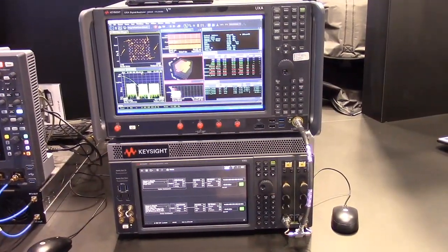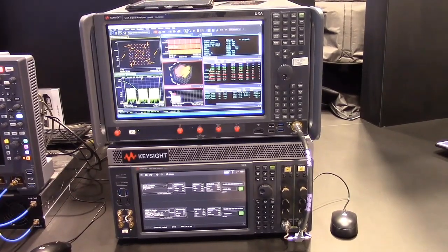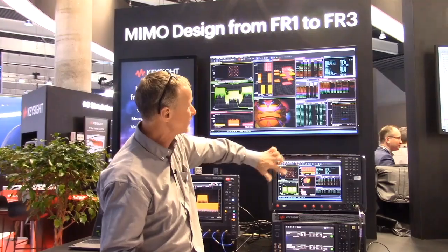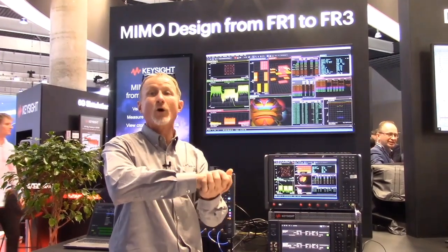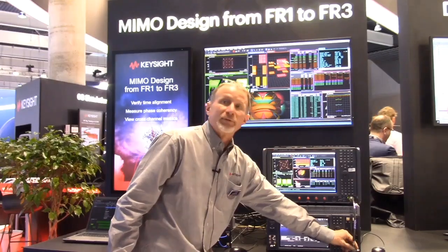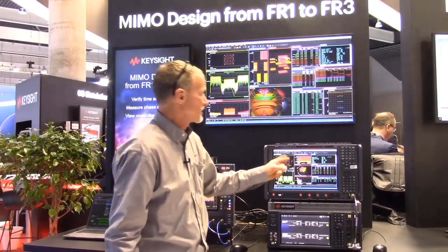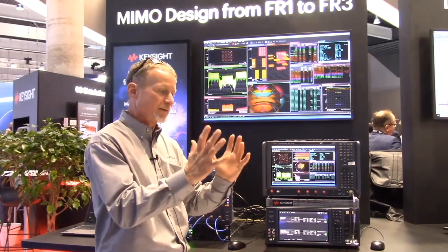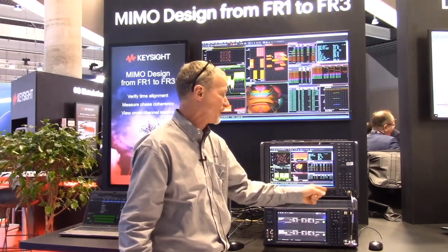If you look at the orange user here, or the orange part of the constellation, we see that it doesn't look quite correct. The reason for that is because the data is overlapping and interfering with each other. Since we're combining both layers onto a single channel, it's causing that. Normally, if you wanted to demodulate the data from each layer, you'd need a separate channel.